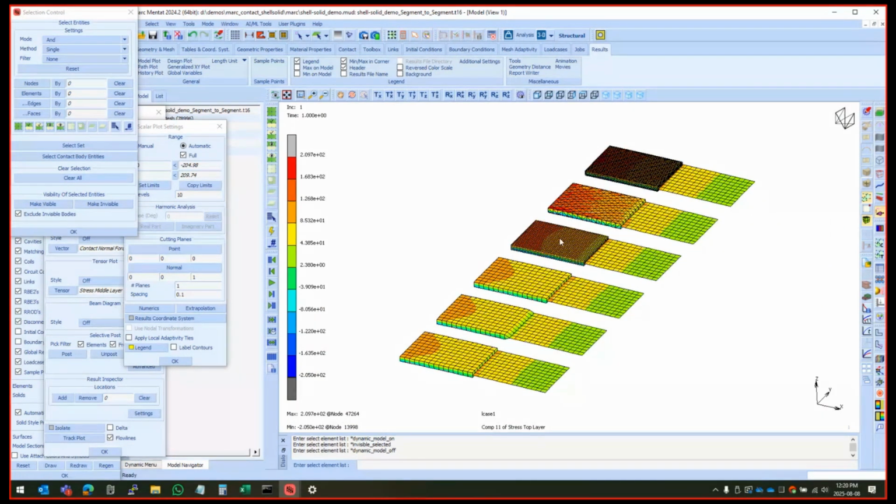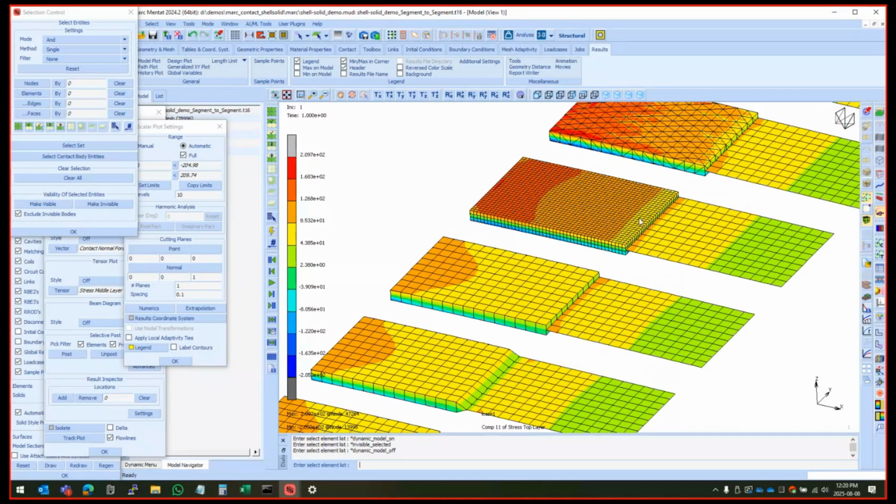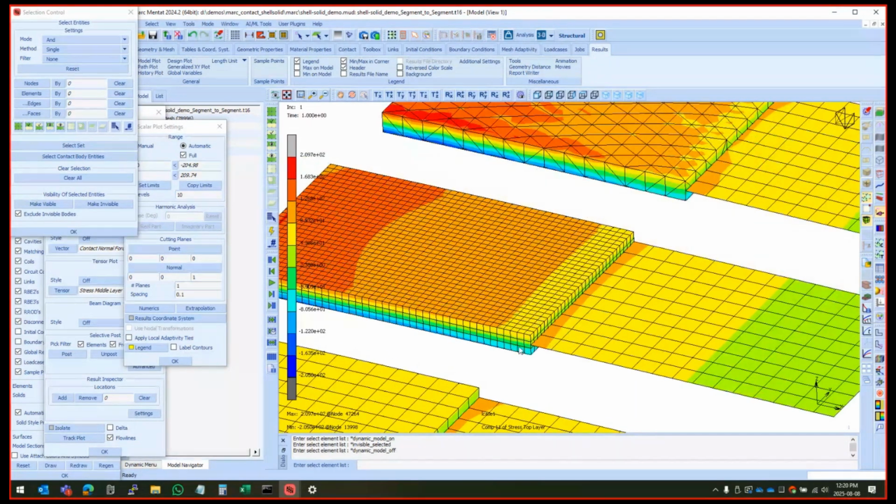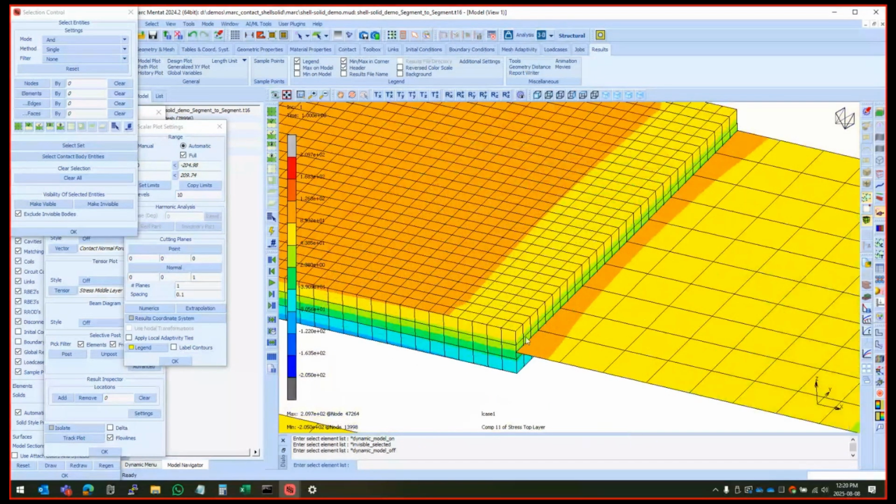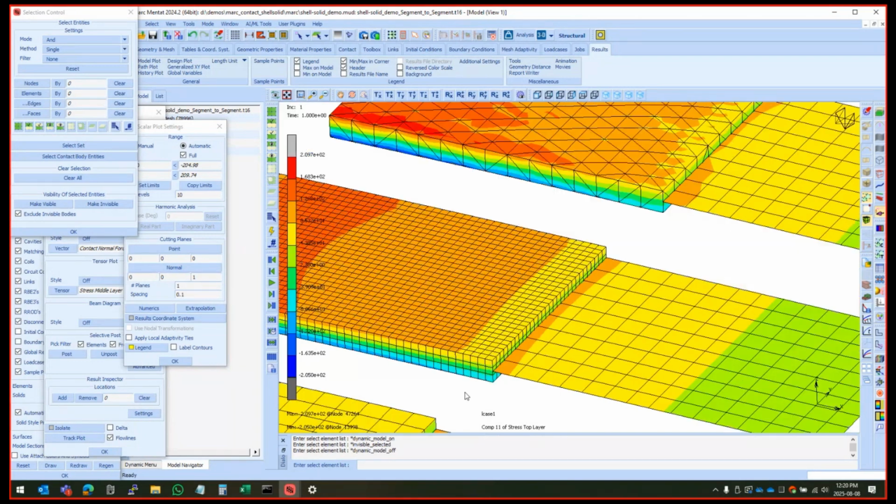I need to mesh finer to get the converged stress, which means effectively, while these are useful, they're definitely not perfect, and I'll rather go for one of these kinds of methods. So once I get there, I'm forced to use either glue or I have to in some way skin that front face and connect them. But in this case, it won't work because I've got fine elements there and pretty coarse elements in this direction. This is all first order, and first order, so I can make it work.